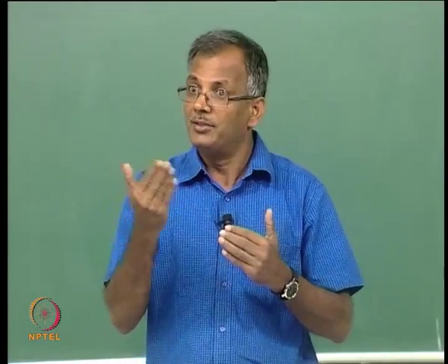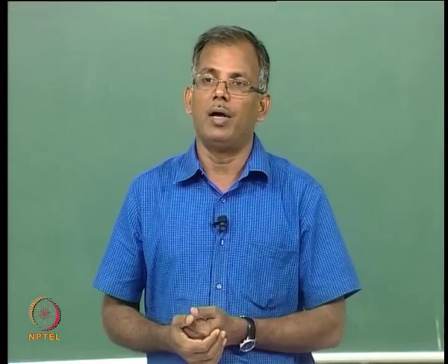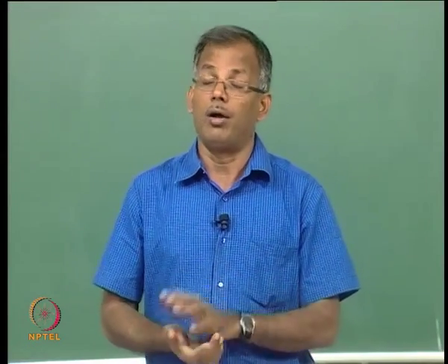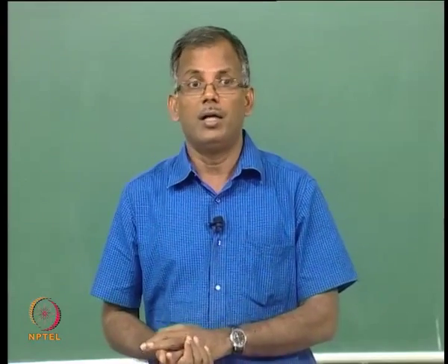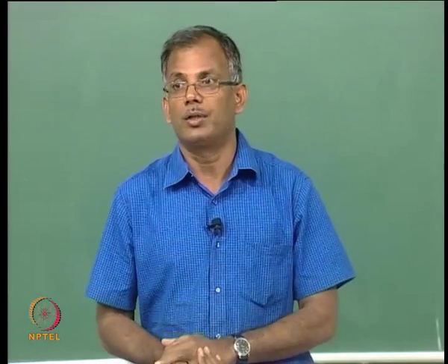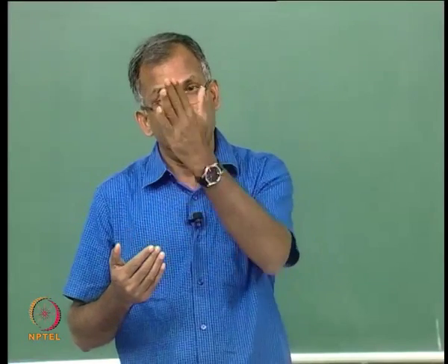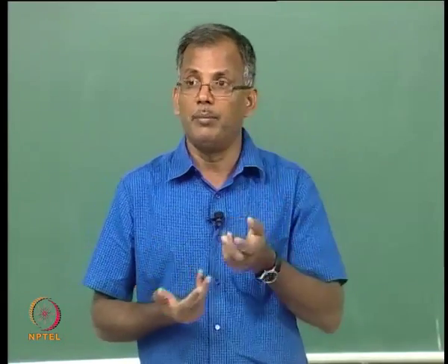So, in any case we may have to do the driving analysis for the restart case, which is because of pile failure or hammer failure or environmental conditions not allowing us to do work. So, establishing this Ru is a very big challenge, because that is going to be a deciding factor. If you do a calculation which is not correct, or if you underestimate or overestimate, when you go offshore you may face problems either way.